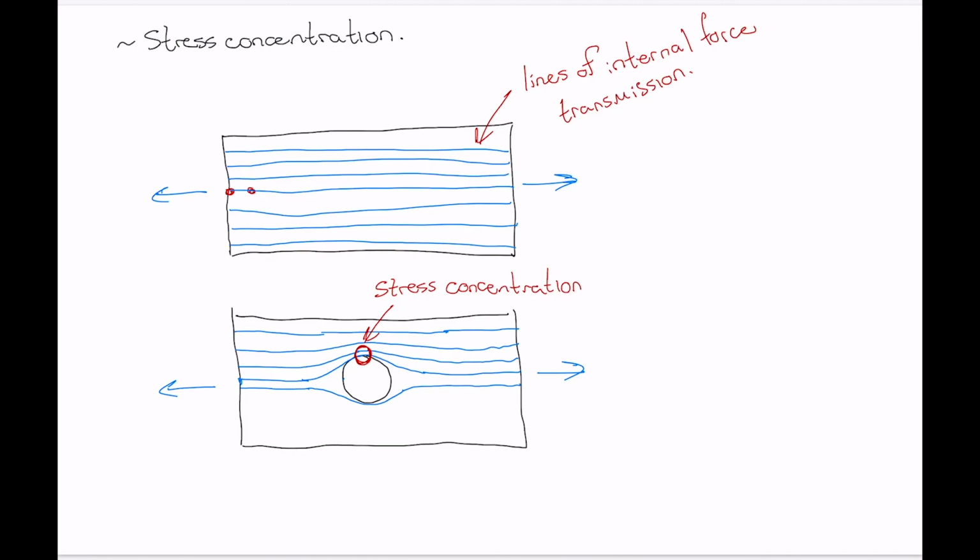At this location, the effect of this stress concentrator, which is the hole, in the stress concentration that occurs, the effect is that the maximum stress right at the point that's adjacent to the hole is going to be significantly higher than the stress that you would calculate just by doing your normal force divided by cross-sectional area at that location, calculating your average normal stress.